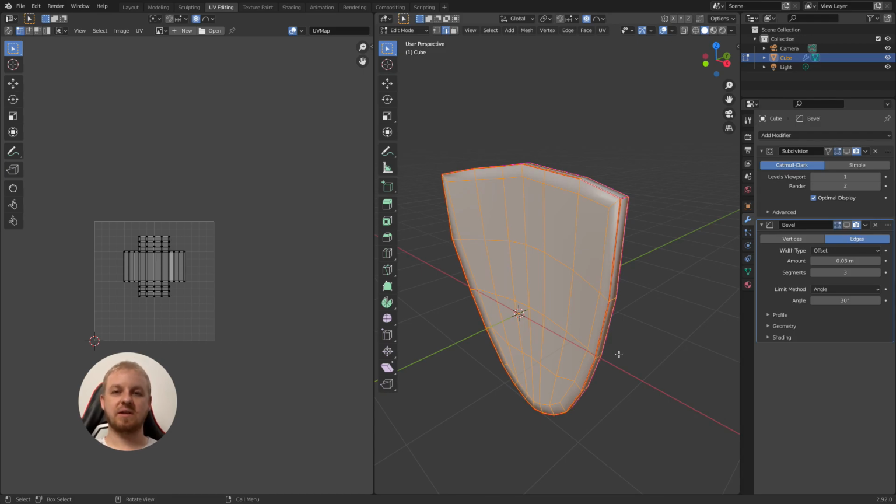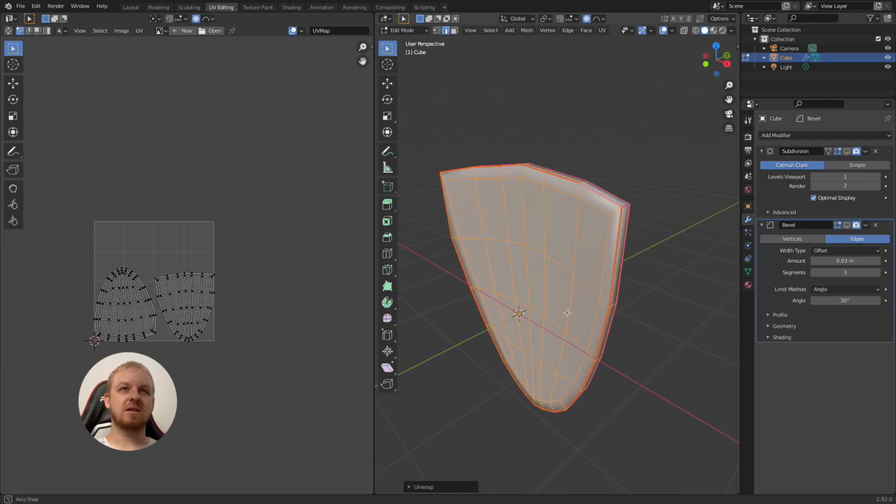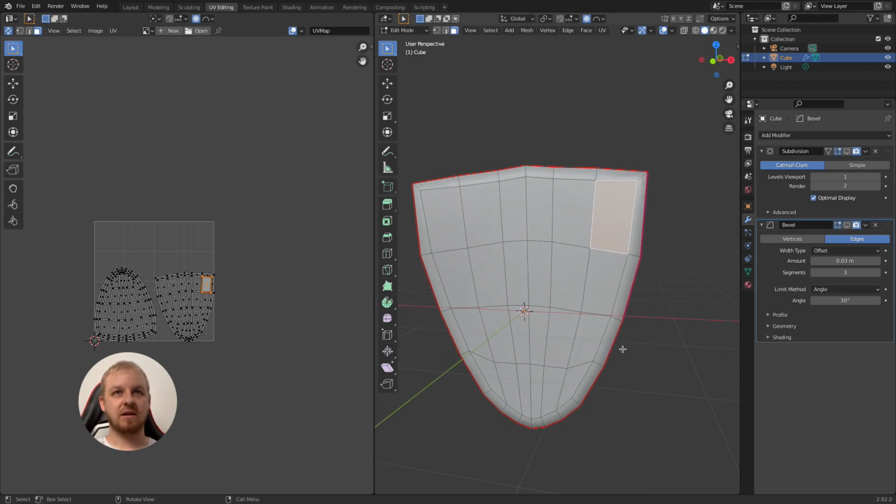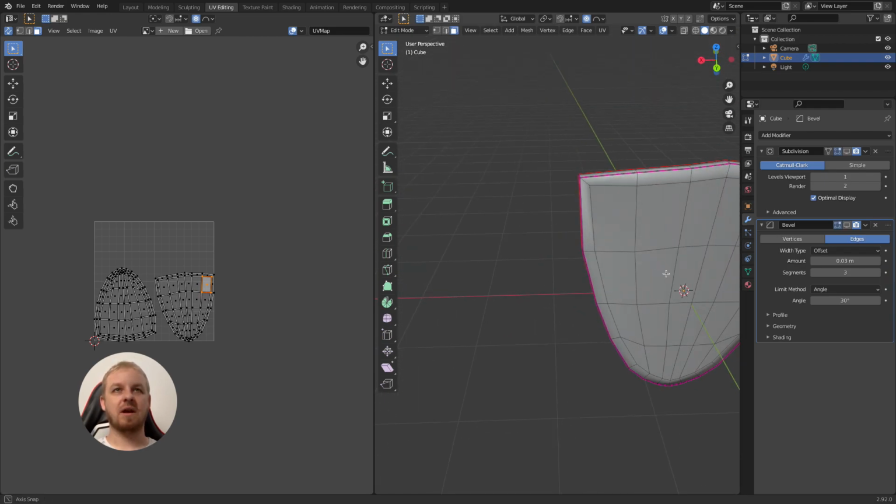The seam is basically how we want to cut our 3D mesh to project it to 2D, like with a soda can or something that you can wrap the flat surface around, like the print on the 3D object. And now press U again, unwrap, and now you see what I'm talking about. Maybe I'll select it like that and use this, and this will always show full UV, because if it is not selected it only shows the faces that are selected, right? So this shape here is basically the back, and everything else is front.